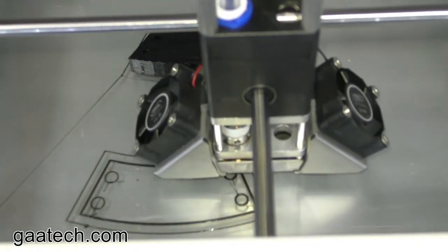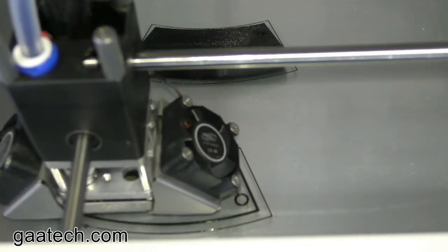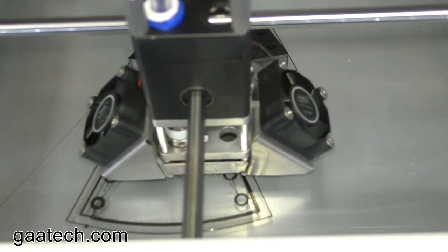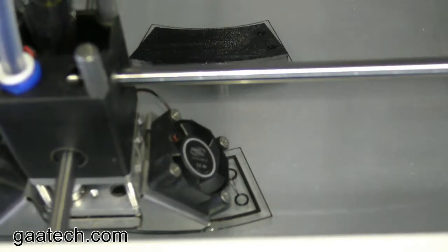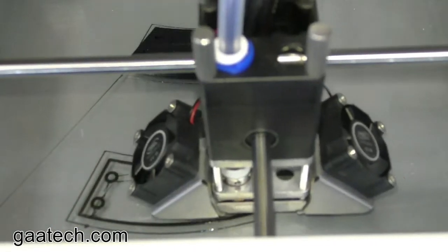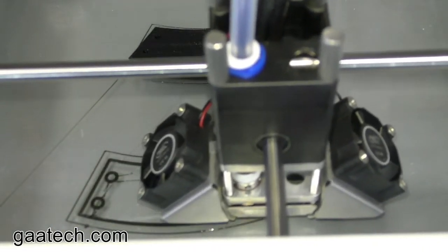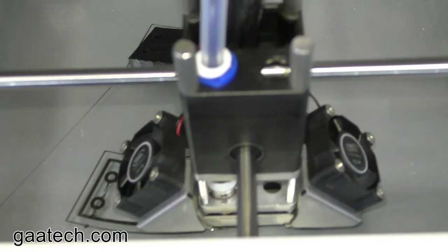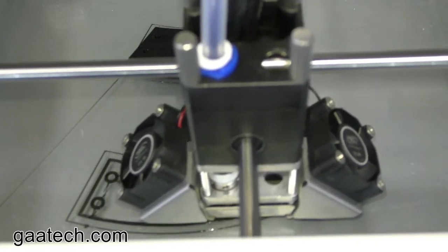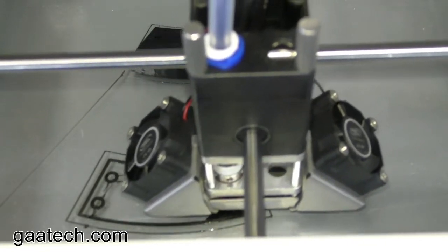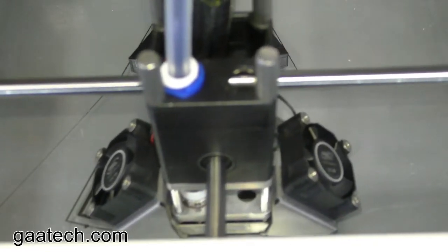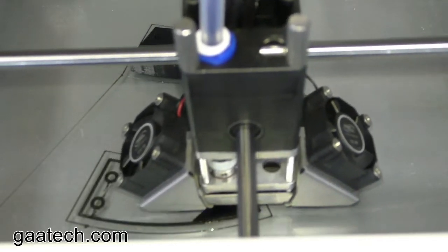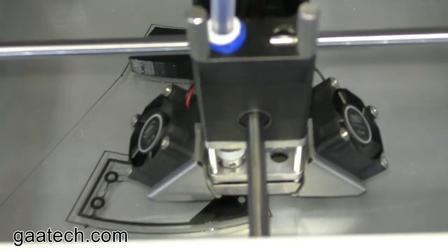I adjust the print speed to a slower setting. I believe it was 30 to 40 millimeters a second, and that's just to make sure the initial base layers stick to the build plate. If you extrude it too quickly, you can have the corners peel up. So the printer is slowed down, and then once it's done the first 4 layers, the print speed will jump